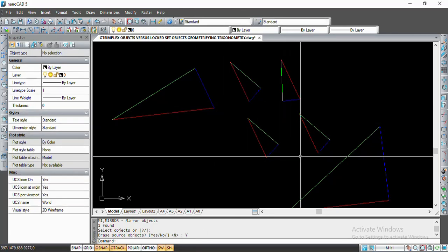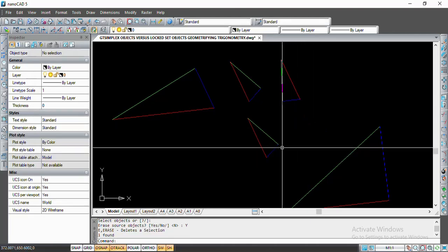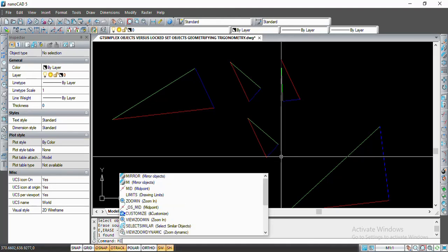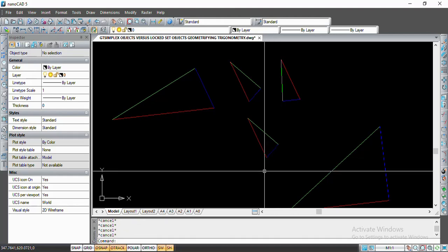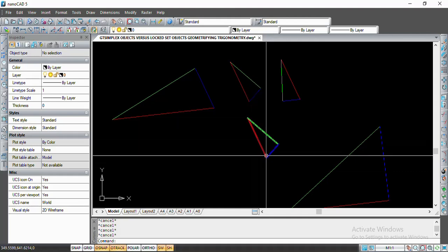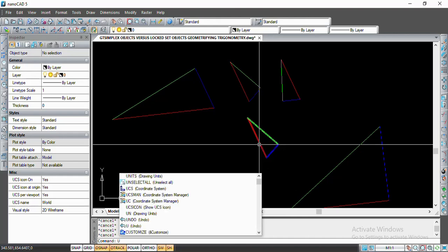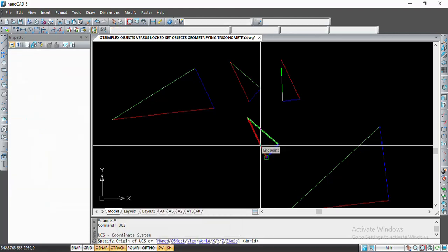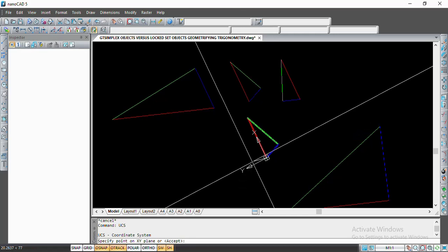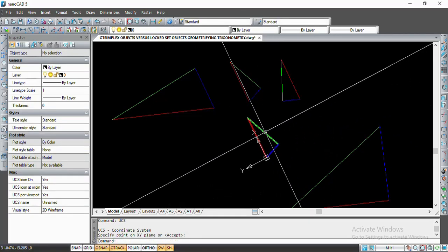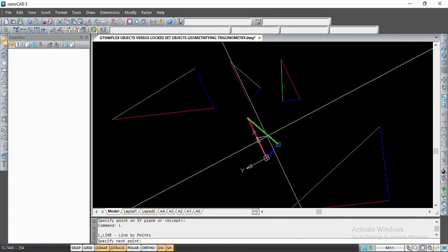Now we want to do the mirroring of this object which I have kept intact here, which is mirroring or which is just rotating of these things. Suppose we want to draw a perpendicular on this line segment. The best way to draw a perpendicular in CAD here is we can set the UCS, user coordinate system, to this line, and when this line is the user coordinate system, now we can easily draw a line segment to the midpoint of this, and that is the mirror line.